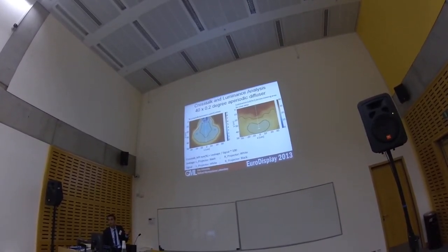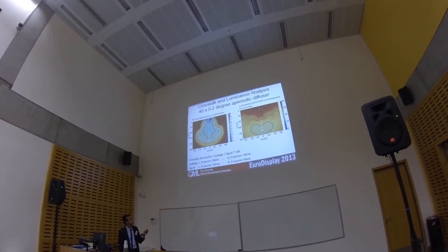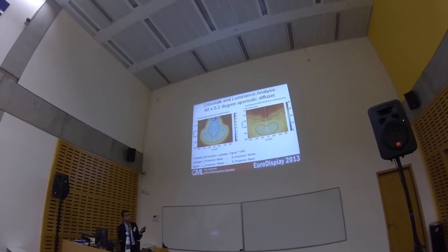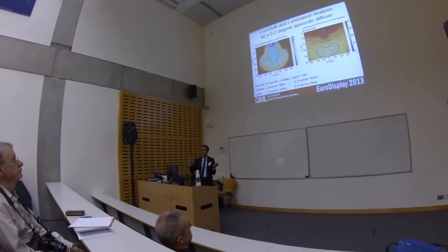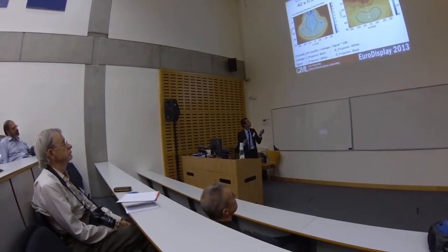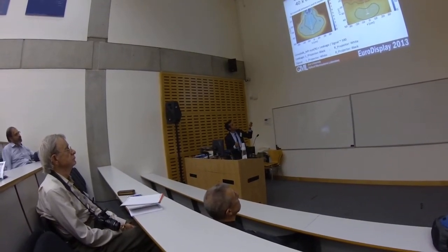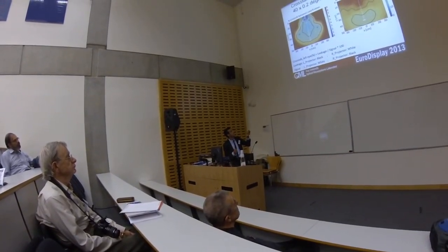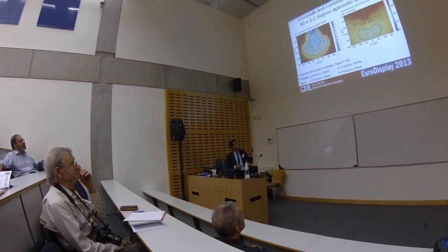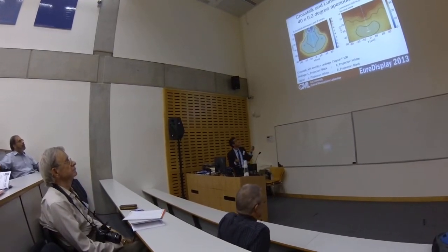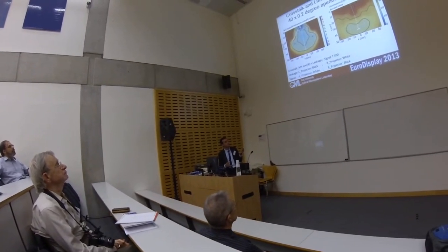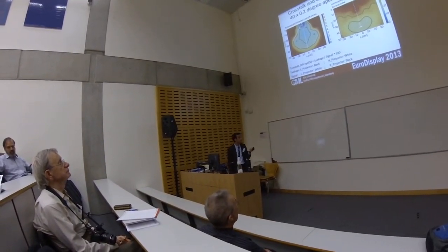And these are the brightness values, the luminous values. As you see, the brightness is very high when we are close to the projector, and it decreases because of the beam profile of the linear diffuser. The diffuser that we used was a periodic diffuser, with a 40 degree diffusing angle in one direction and 0.2 degree diffusing angle in the other direction. When we calculate the projection distance and the diffusing angle, it's approximately the same. So the experimental results confirm the theoretical results.